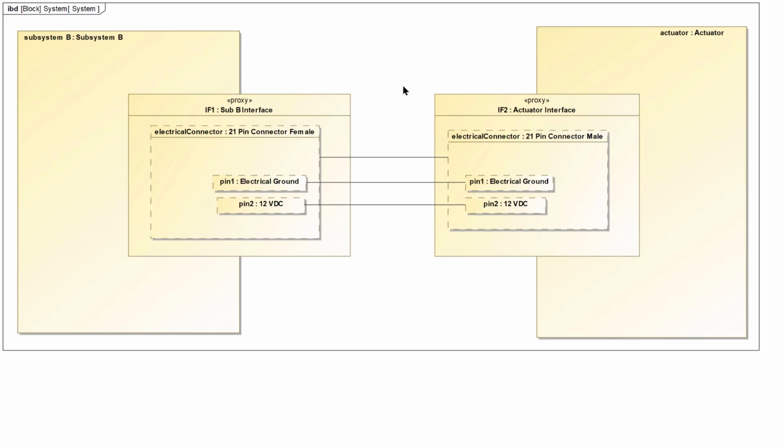And if you were to simply create an out-of-the-box Whitebox ICD that Cameo has available, what they do is they bury some of the script that actually parses out each side of this, which creates one column that shows one side of that and another column that shows what's in the other side of that. So if you were to try to recreate that on your own in a generic table, what you would find is that if you simply query that connector and then the ends, you'll get both ends in one column, and you don't get that mirrored side of that, so to speak, to see what connects to what.